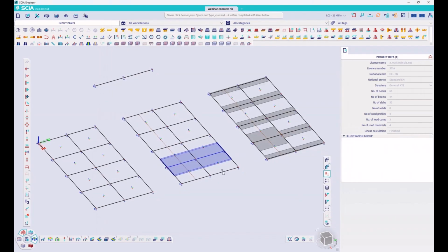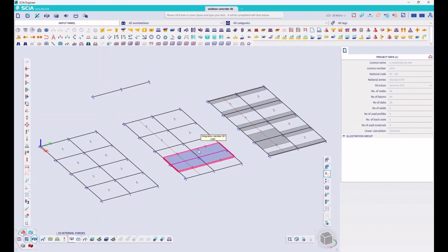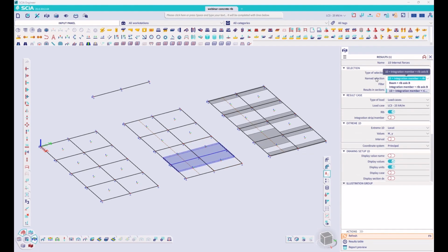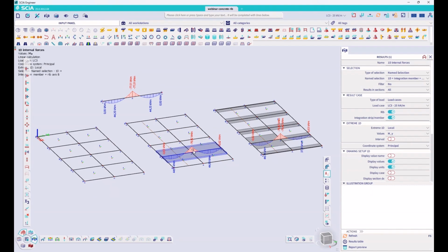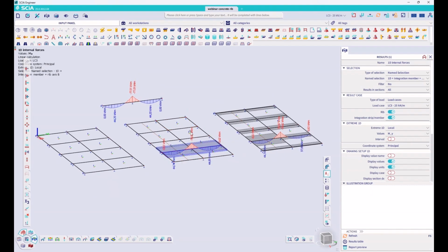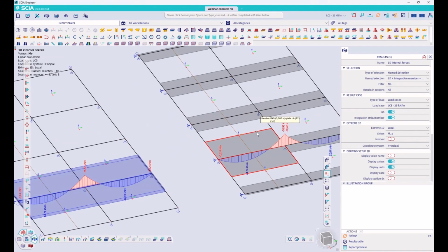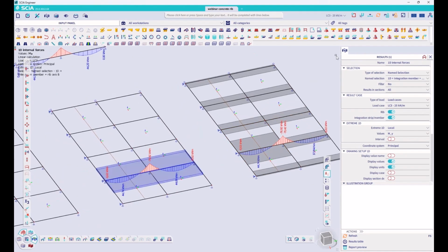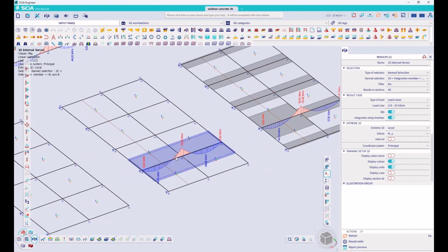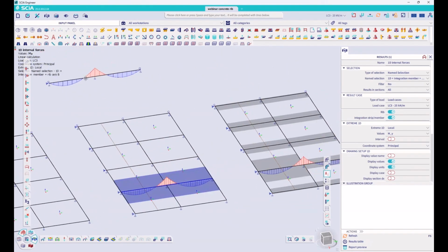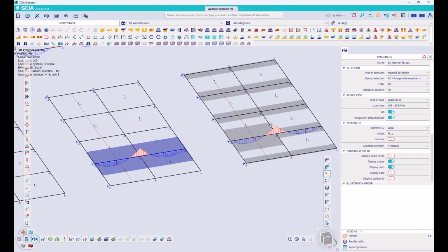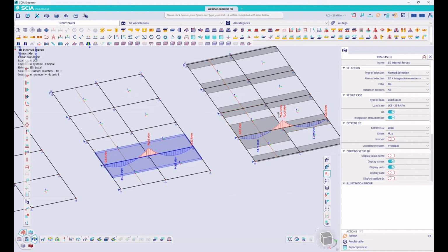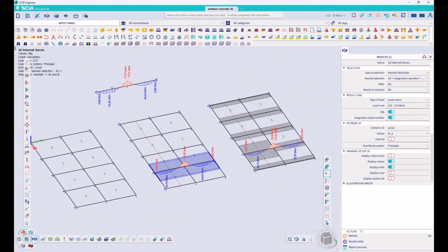And so let's take a look. If I go back to the 1D internal forces, if I take a look at my rib, my integration member, and my 1D member, I can see that for the moment forces, I'm reaching that 77 kilonewton meters for both the rib with 5 meters of width for the internal forces, as for the integration member, as for the 1D element. So in those additional 3 meters of plate, I've taken up all the forces, so I'm reaching more or less the same values as in the 1D element.